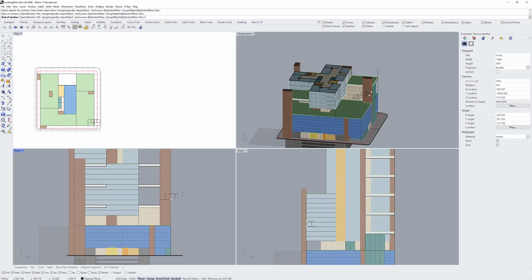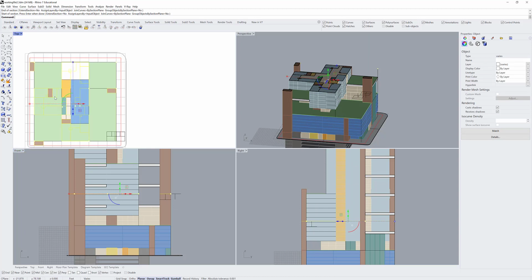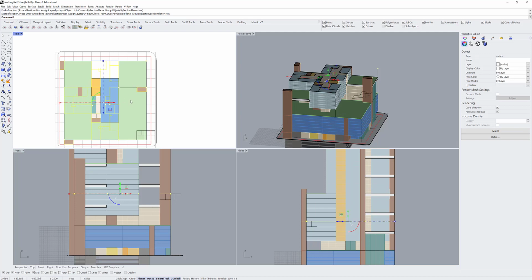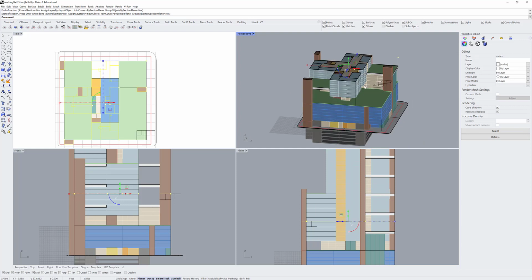And then I'm going to draw from one side of the building to the other, making sure that it's on the ortho. I'm not cutting somewhere else. And that's it. I can right click or hit enter. At this point you have a section of your building. You can actually see it here, but it's right in that cutting plane, so we might have some issues finding it, and we might have some issues importing it into Revit.